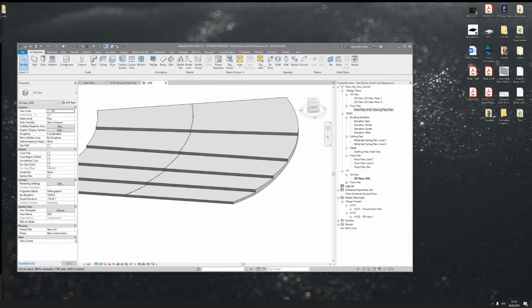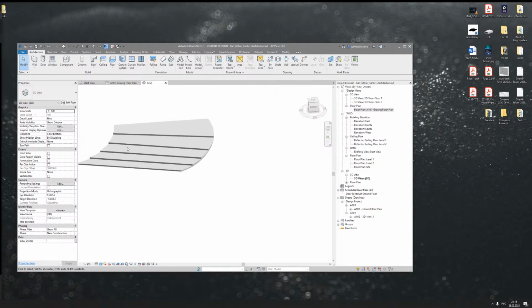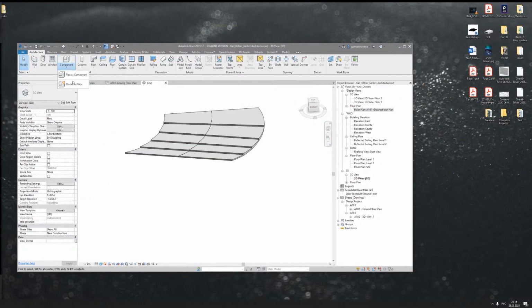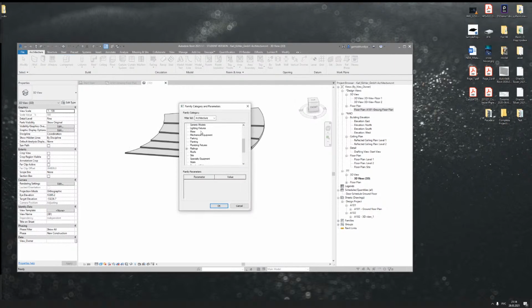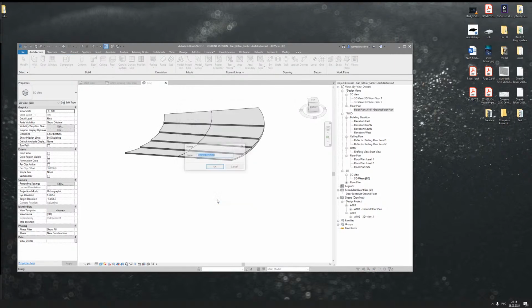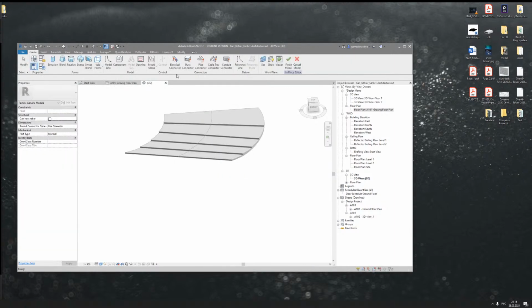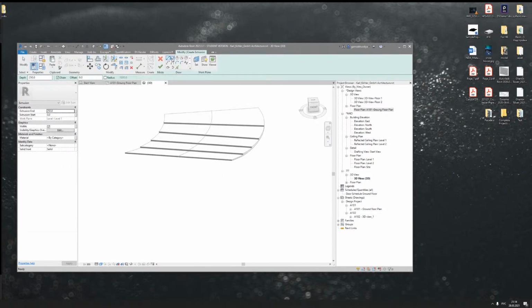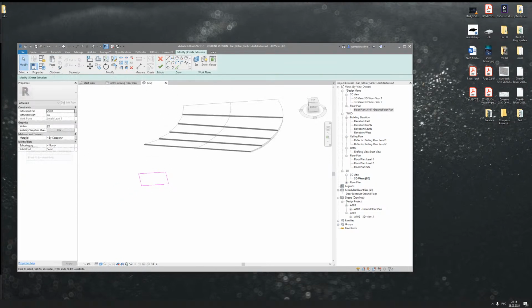You are talking about the material. I can see your question about the material in model in place. And what problem do you have in model in place? Let me create some model in place, for example a generic model, right? So here is the generic model. I will not create some special thing, so we will just make a cube, okay? So here is my cube. And as you can see, here is the material. And you're saying you create it by model in place to appear in 3D, but you can't.